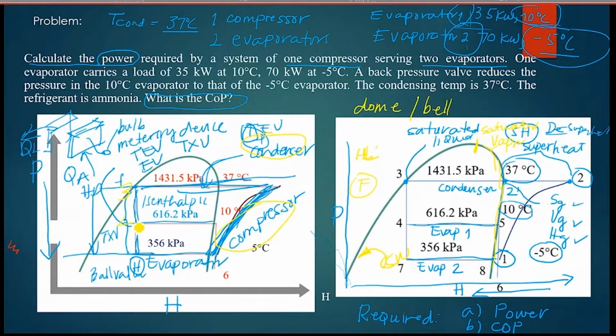So what is the device there? 347 is about the expansion valve, constant enthalpy. If you look at the vertical part, it is constant, meaning a straight line. The pressure is lowering. Look at this. If I may illustrate, this is the liquid line. From the liquid line, it goes down. What is going down? The pressure, right? The pressure is going down, but the enthalpy is fixed.